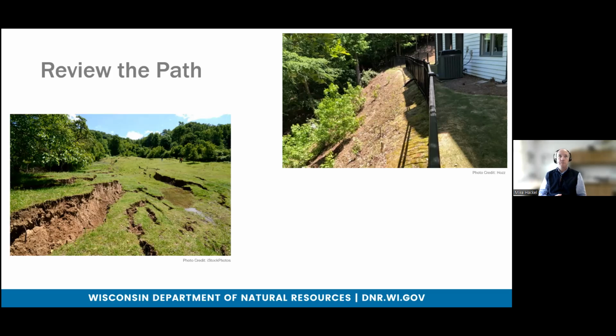And then obviously in that other photo, if we've got soils that are showing evidence of movement prior to any construction starting and instability, we need to be concerned about the viability of utilizing HDD in conditions like this, because obviously the drill hole will not hold, and we'd be greatly concerned about IRs coming up through soil that had this much movement to it.